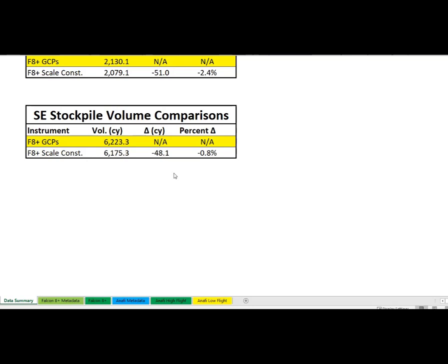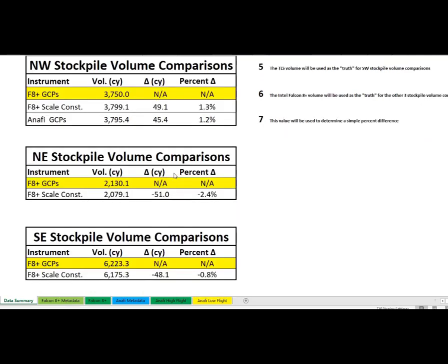So I was pleased with this data in the sense that I think it validates that the drone is a reliable instrument that we could use for generating bare earth surface models. So whether we want volumes or contours or bare earth terrain, no vegetation, it looks like the drone is another tool we can put in our toolbox.